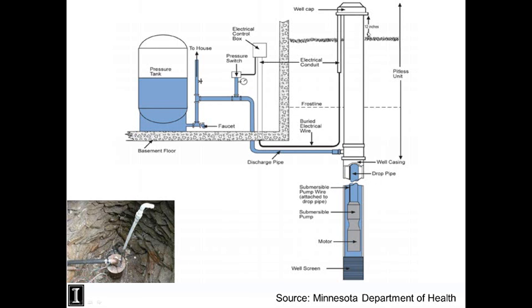installation. And so there are things that are recommended for your well. Have your well 8 to 12 inches above land surface. Usually they recommend you mound dirt up near your well so water always flows away. You have your pitless unit here that runs your discharge water into your house into a pressure tank. And you have your pressure switch, which, when the pressure gets to a certain low point, kicks on your pump to make sure your tank's full.